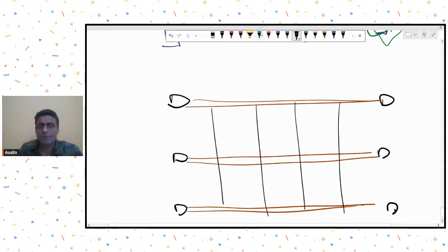Now because I had provided a roller assembly over here, my column over here is sort of acting as a cantilever because it's not getting any lateral restraint from this truss. In such a case, I already have an eaves beam over here. These technical terms, I hope you understand, so I'm not explaining them over here.